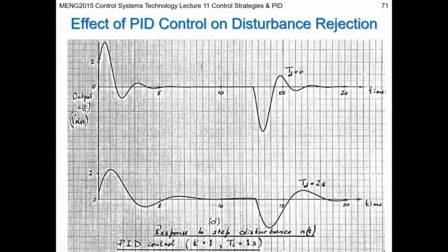So it's gone from up to almost 4 on the output, to about 2. But you slightly extend the response time. So it's a trade-off. Now you're into tuning. Now you're into fettling and changing these values till you get a setup which meets your performance requirements, which you should have set in advance at the start of your design process.